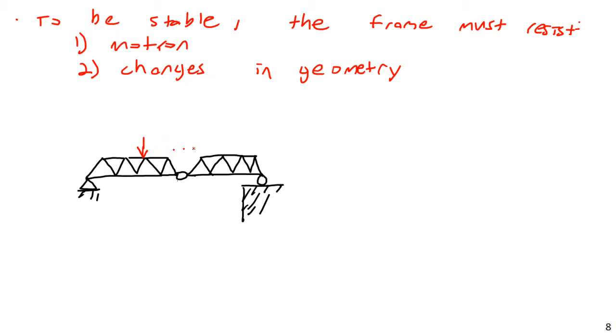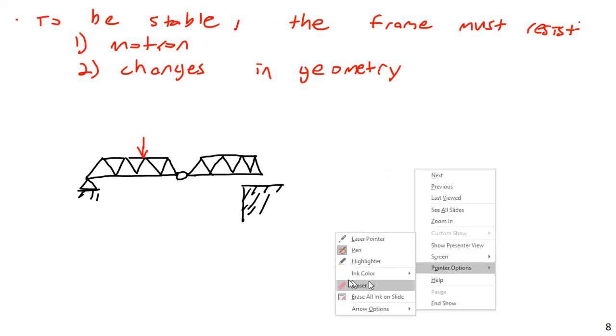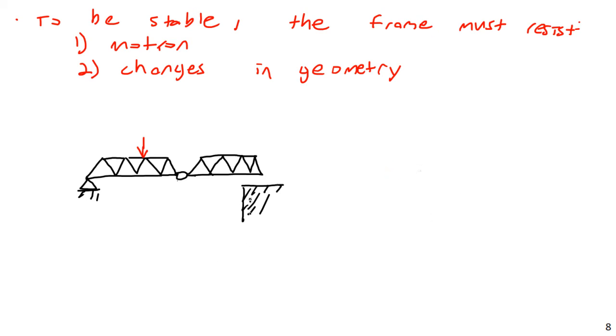The moment I apply any load, or actually even the self-weight of this thing, it's just going to flop down and basically fall into the river here, or whatever is here. And in fact, even if I made this a pin support, the same problem would exist. So even if this is a pin support as well, now this truss is completely stationary. It's not going to move left or right or anything else, but it's not going to have any bending moment capacity.